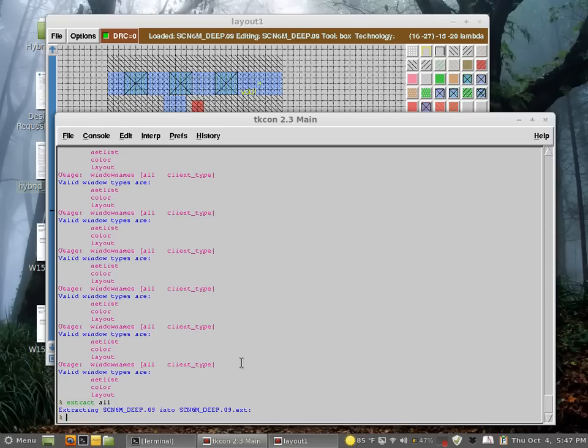levels of cells. So when I do extract, it makes a netlist, but in a format that's not useful for me, in a format that's compatible only with Magic, which is in a file called, by the way, oh, I forgot a very essential step, which is to save my circuit. So to save it, I just do the command write.